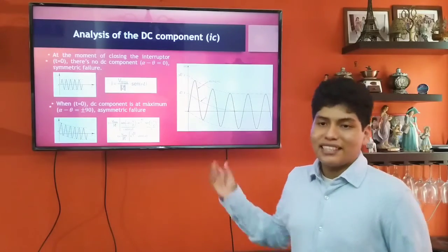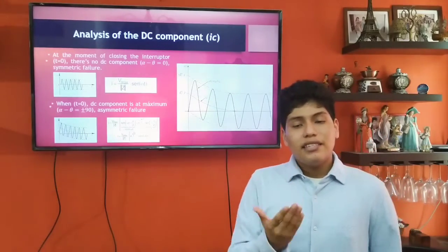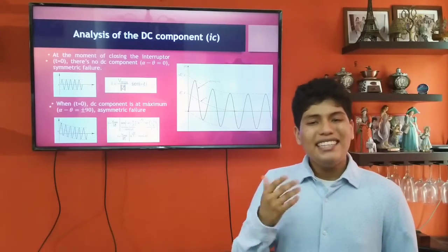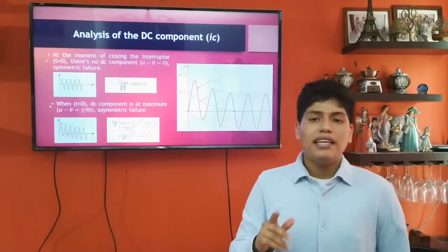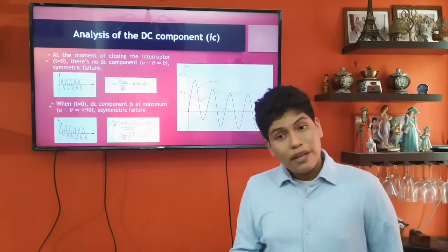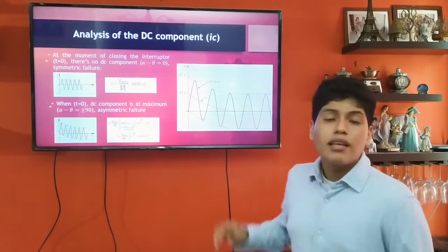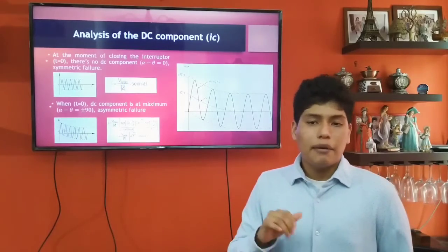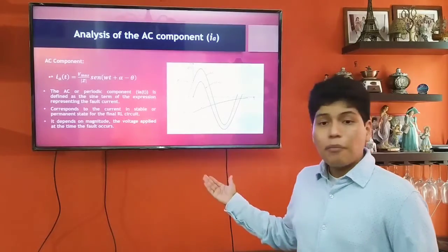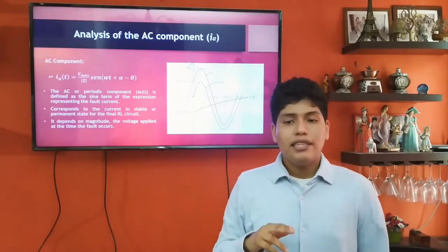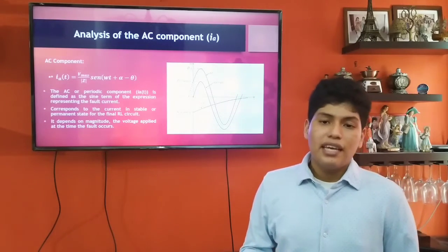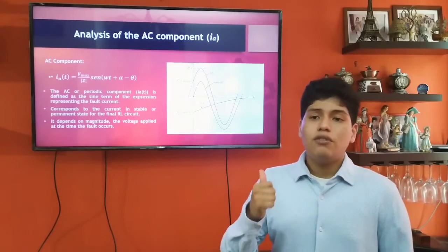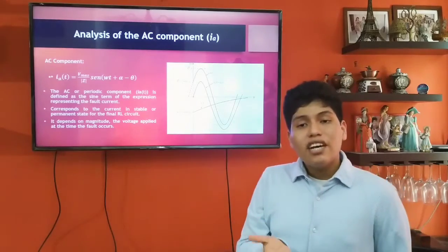The DC component is the component present only in the transient state, which allows us to determine the magnitude of the resulting current at the instant of the abrupt change until it manages to stabilize. This component presents an exponentially decreasing behavior. It can reach a higher value than the current peak of the equivalent stable system. The AC component, also called the periodic component, is the sinusoidal component and is maintained in the stabilized state. It is the component that suffers displacement because of the DC component.